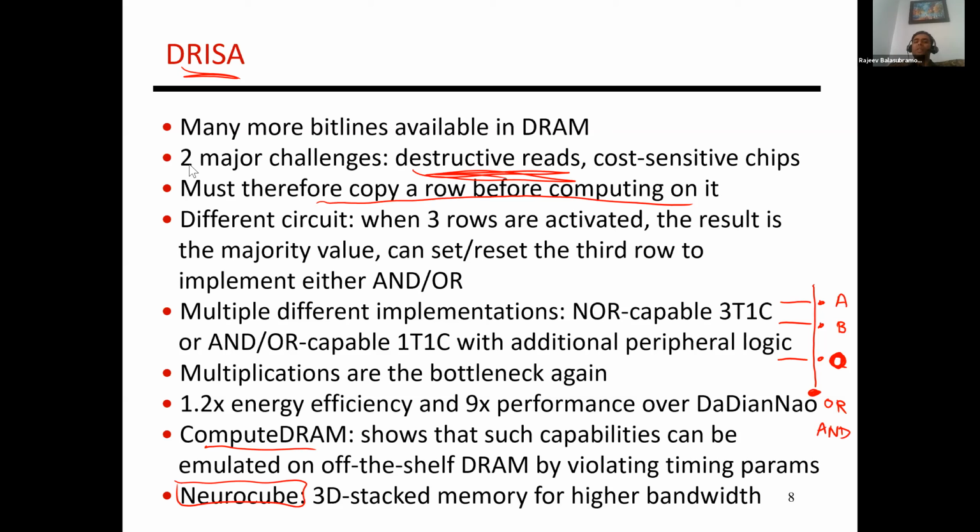And so, these SRAM arrays are so well understood, they're designed for very high density. And so it's understandable that industry will always have a little bit of pushback in terms of modifying what is a well-known and dense circuit. It all comes down to, are there enough applications that can exploit this? Once you make that case, then I think folks within industry are willing to accept it and make it part of the products. So the main issues are the trade-offs in terms of complexity, power, latency, clock frequency, and so on. And so it always takes a little time for it to mature.